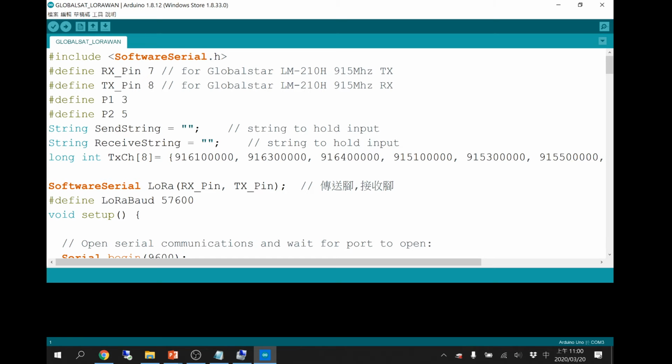For the RX, please connect to the pin A. And here is to the pin 7. So guys, please do that. You need 4 wires. But for example, if you can buy some kind of this wire, it's much easier for you to connect.